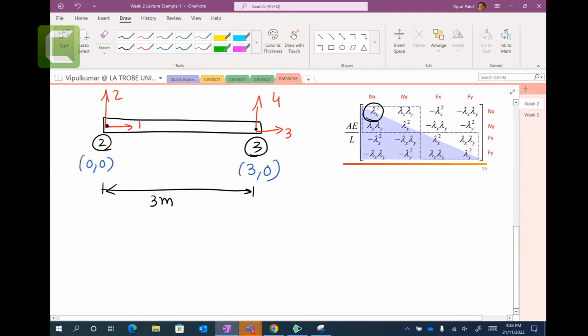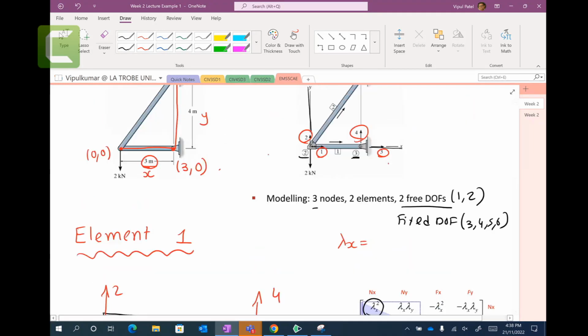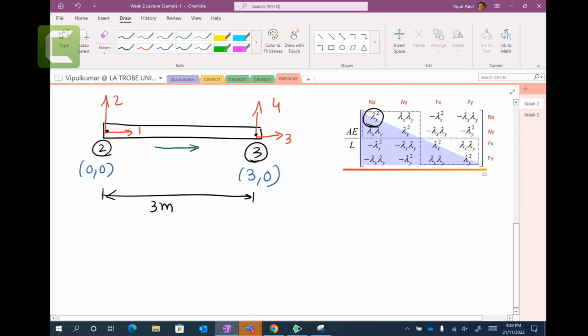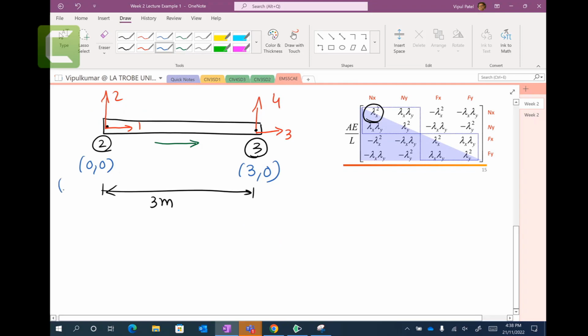So this one I can put in the arrow. These ones are location vectors. Let me put the location vectors here. Now here I can put x1, y1, or let's put near node, far node, because we already know that. So this is the near node and far node based on this arrow. The tail of the arrow represents the near node, which is node number 2, and the head is the far node. So I can say x near, y near, and x far node, y far node.